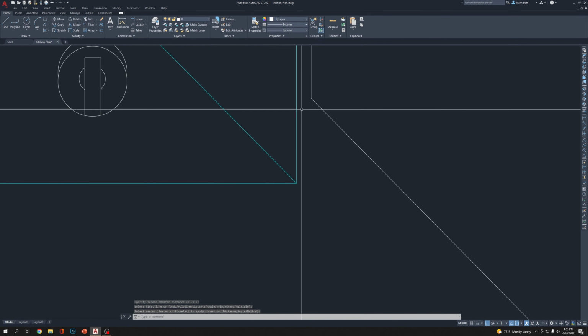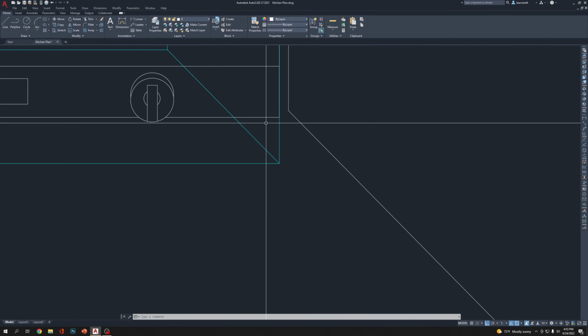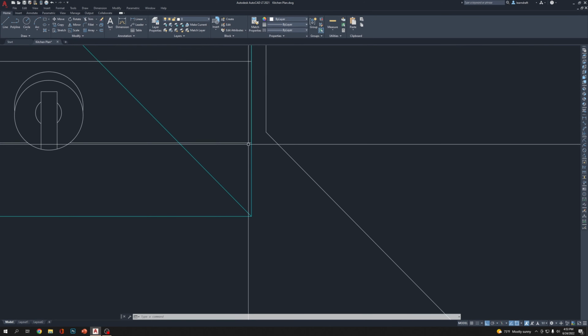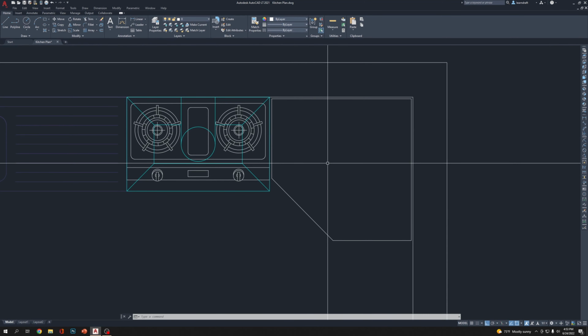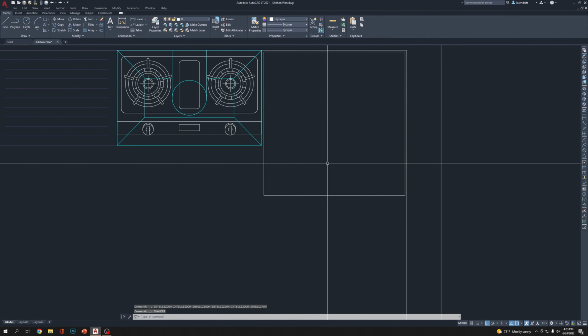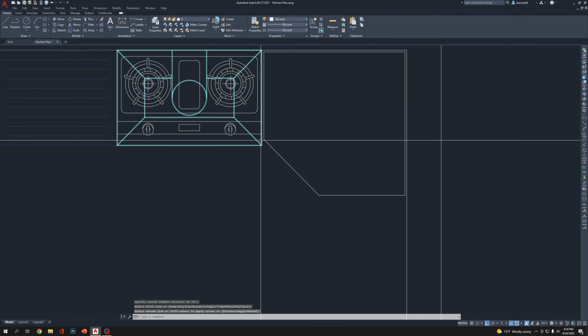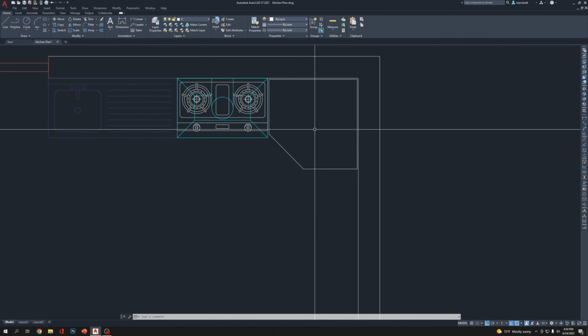But it's not going to be a line, it's going to be a little inside, and it must be aligned with it or a little out. So 9 inches is too much. Control Z, Control Z. So CHA, enter, D, enter, 8, enter, enter. Why twice enter? Because this is going to be 8 inches, this is going to be 8 inches. If you want 8 by 10, you can do it. So we have 8 by 8, and I think we're good.